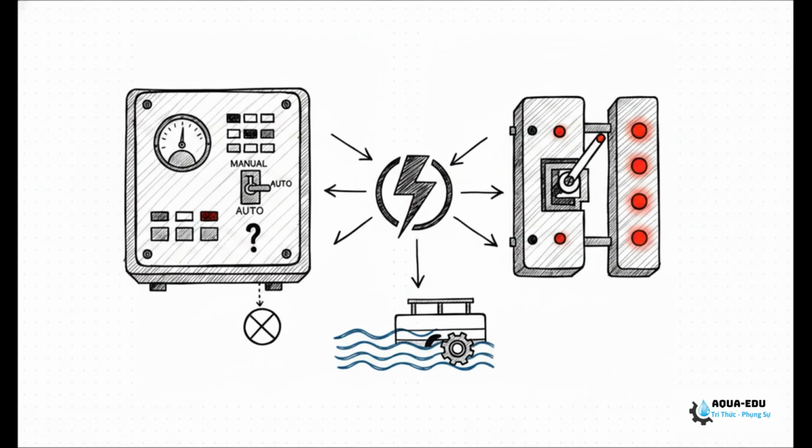I really can't emphasize this enough, brothers. These backup systems are notorious points of failure during an emergency. Make sure you check if the generator's control panel is actually set to auto and hasn't been accidentally left in manual mode. Inspect the ATS panel super closely for any red fault lights or mechanical misalignments that might be preventing the switch from closing the circuit.